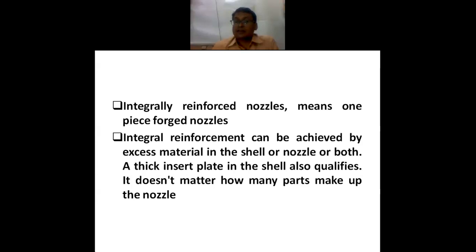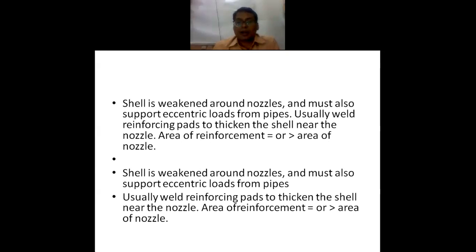That means instead of a reinforcing pad, I can provide higher thicknesses for the nozzle and higher thicknesses for the shell. So a thick insert plate on the shell also qualifies. It doesn't matter how many parts it may be.